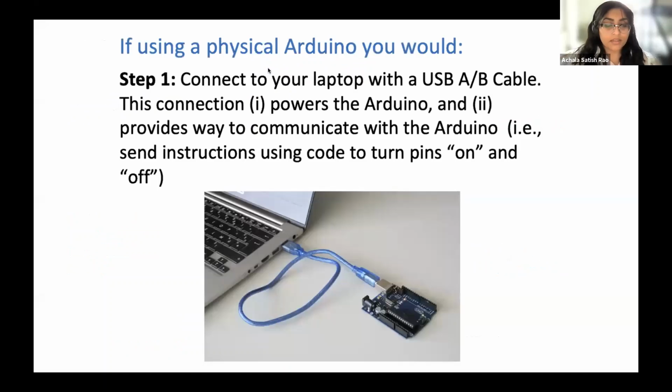So if you're using a physical Arduino, the first step that you're likely going to take is connecting your actual Arduino to your laptop. You're going to have to use a USB-A or B cable, and this does 2 things. 1, it powers your Arduino, and 2, it provides a way for your Arduino to communicate with your computer, right?